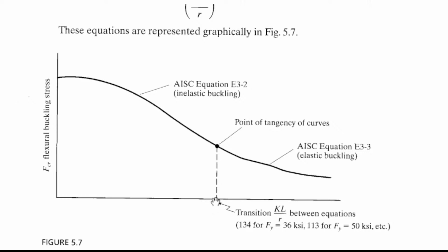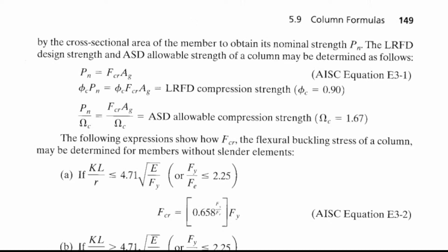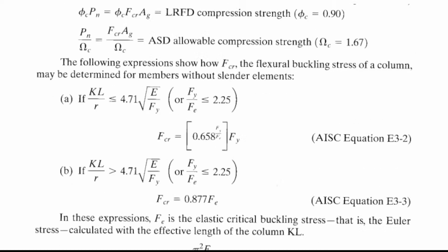This is the point of tangency of curves 1 and 2. This is elastic buckling, our Euler, equation E3-3. Inelastic buckling is equation E3-2. So refer back.